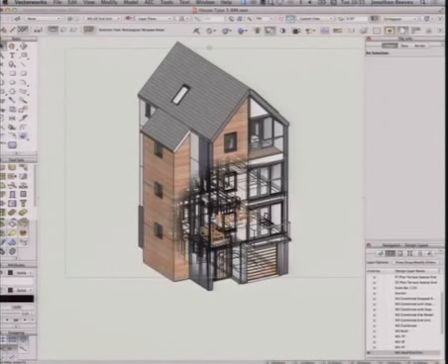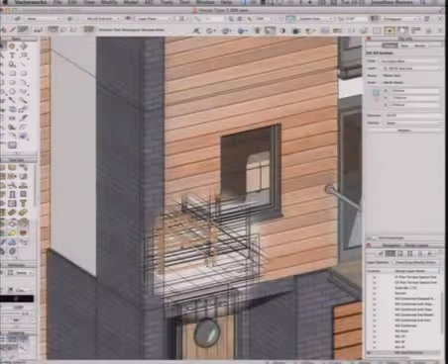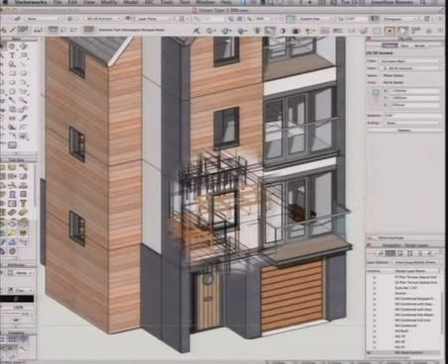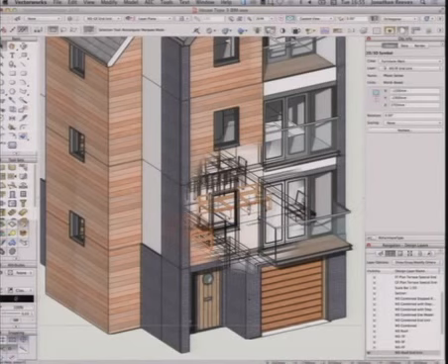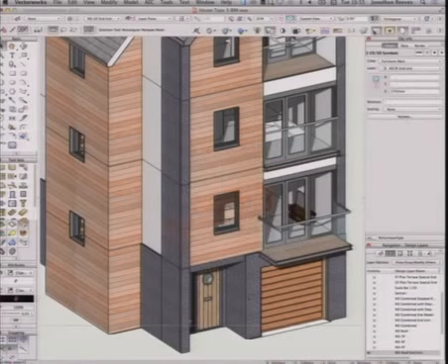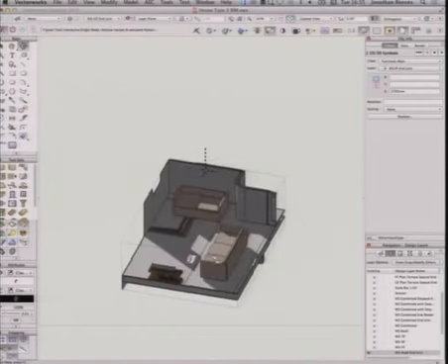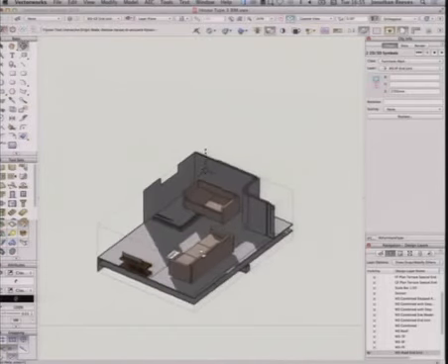Did I get that? Not sure I did. Let's go good old-fashioned scroll in. Select that. So I've got some stuff in there selected, hopefully. If I click the clip cube now, what it does is very clever. It isolates the geometry just around that bit of the design. So it's a fantastic tool.